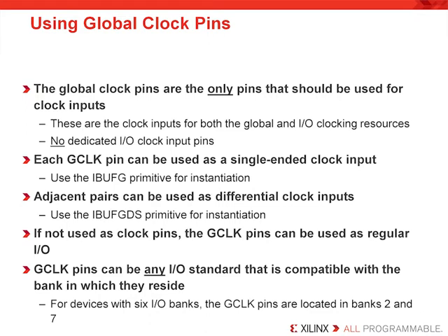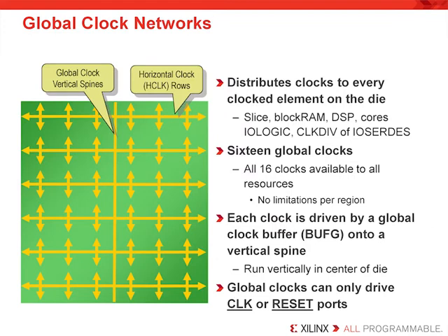even in the larger densities, so pay particular attention to this when planning your design pinout. Global clock networks can distribute a clock to every synchronous element in the device. This includes registers, block RAM, DSP slices, cores, I/O blocks, clock dividers, and SerDes resources.